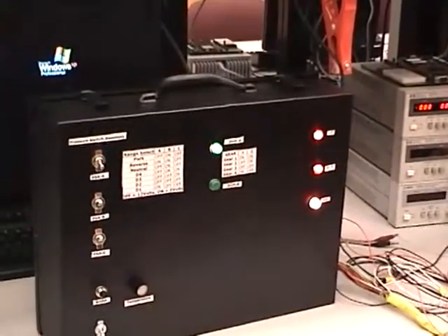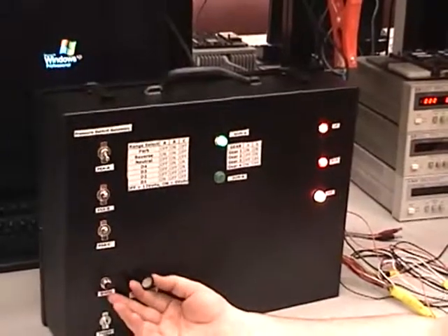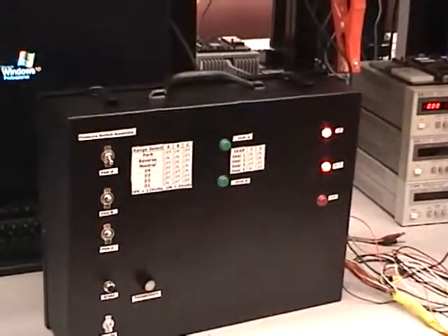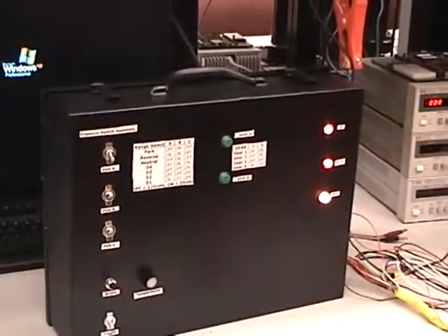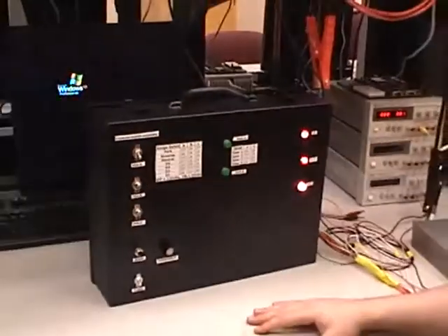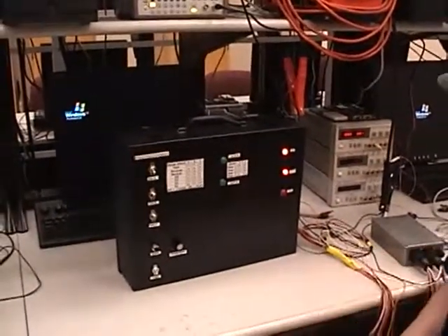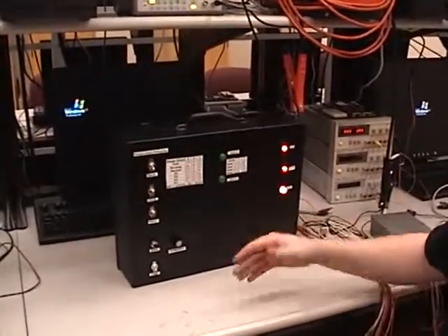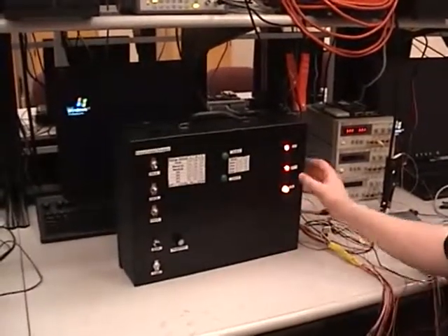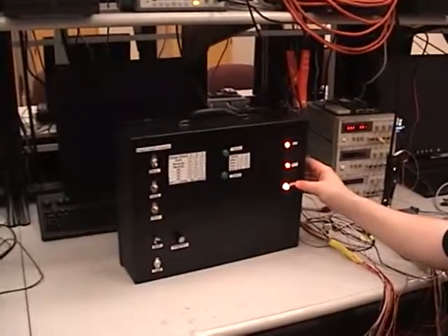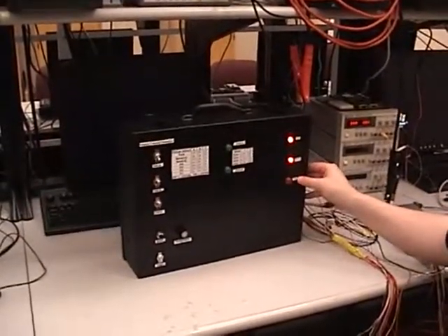Now the opposite, the extreme, is if the engine overheats, and we'll simulate that by turning it counterclockwise, and you'll see if it overheats, the car goes out of 4th and into 3rd gear, so the transmission is causing less friction and producing less heat, making your RPMs shoot up on the engine, but at least your transmission has time to cool down. And then also your TCC, even though before it was not supposed to come into 3rd, now it's being forced on, which you can see right here.